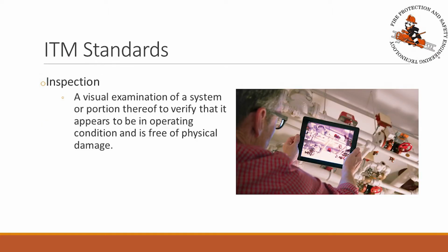For ITM, inspection, testing, and maintenance standards, there are three different types of activities that get specified. First, inspection is a visual examination of the systems. These inspections tend to be done at relatively high frequencies because they're non-invasive. Literally all it requires is someone to walk by and visually observe, does this look like it should? If everything's unobstructed, open, clear, whatever the criteria are, then it's fine.